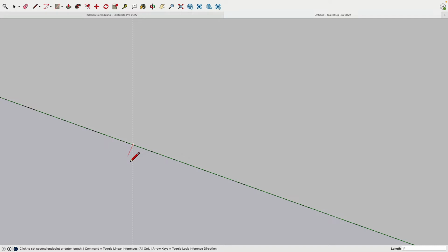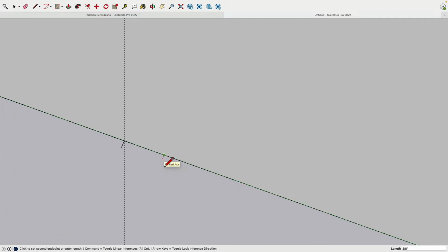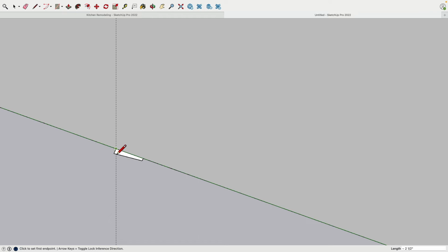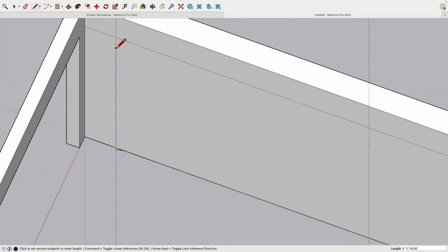So along the x-axis, 1/2 inch. There we are. From this point along the y-axis, 2.5 inches. Along the x-axis, 0.25 inches. And then we can connect this. And then here you see how I'm drawing the path for the follow me command. Correct.